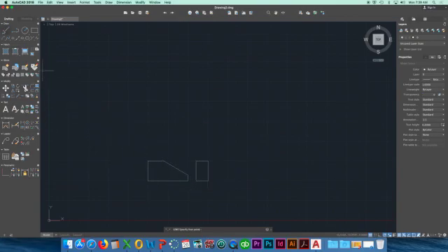Click on the line tool. Now that's part of the front view. We're just missing one little point. So where this end view is, I'm not clicking with the mouse, I'm just going to the right, and it gives me a little green dotted guideline. Click on the first point, click on the second point, and now I've got my front view done.